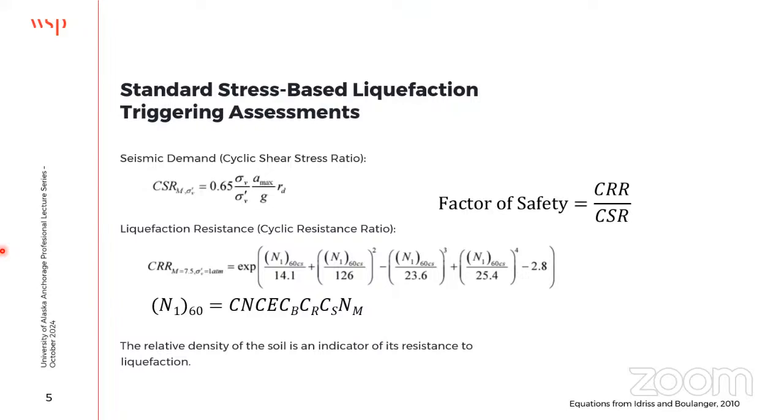Now, one thing that's important to know is that when you're out in the field and you have a field set of blow counts, that's a good starting point, but it doesn't correct for a lot of different things. Joe with this hammer or John with that hammer may have different approaches to driving that sampler, so we've got to correct for the energy of the sampler, the depth of the sampler, and the diameter of the borehole.